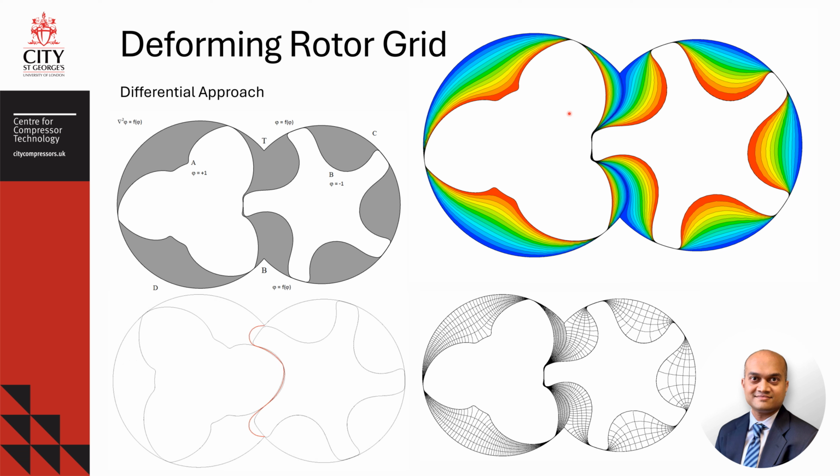Similarly, the boundary conditions can then be flipped and isolines can be obtained in the orthogonal direction. A superimposition of these orthogonal lines is basically a representation of the two-dimensional grid as shown here. In place of the rack curve, which was used in the algebraic method, an iso-value of 0 in this particular boundary condition setup is shown in this animation. It can be seen that this particular isoline partitions the domain neatly into O-grid structures.